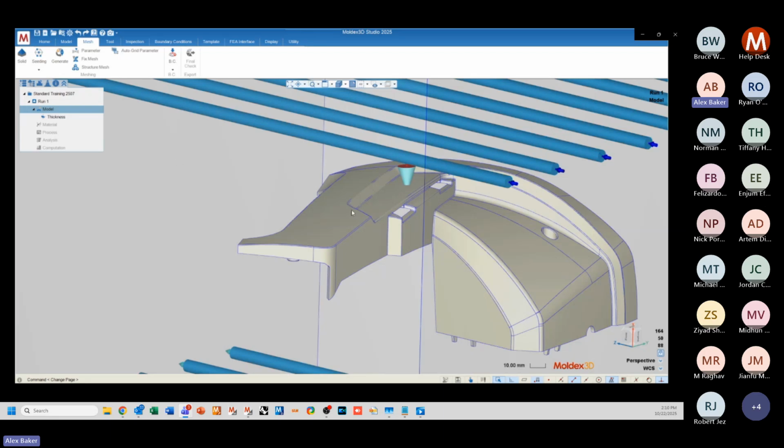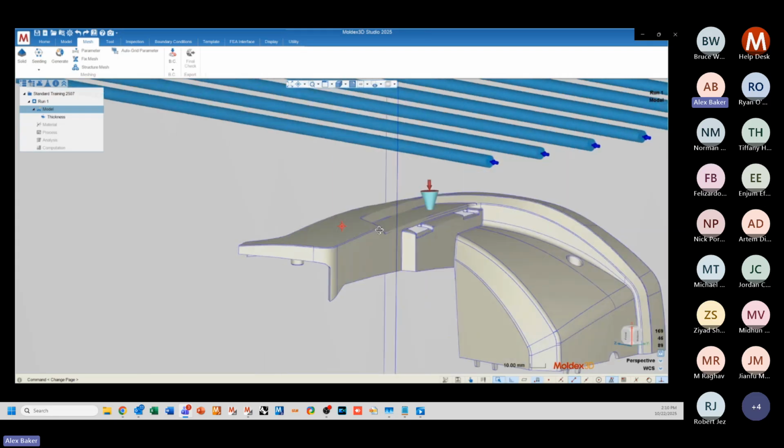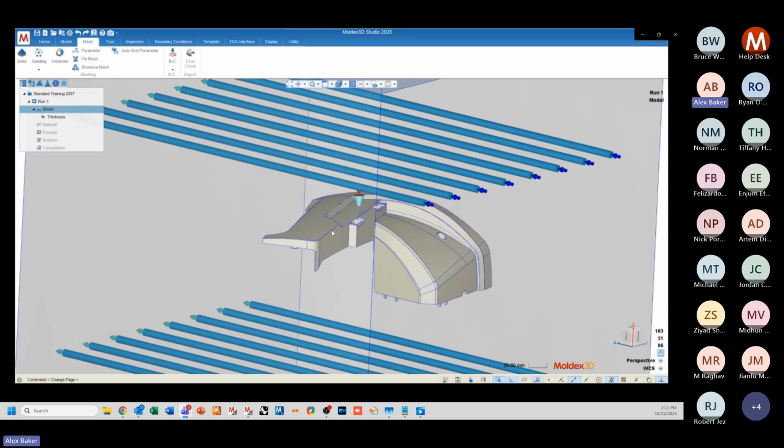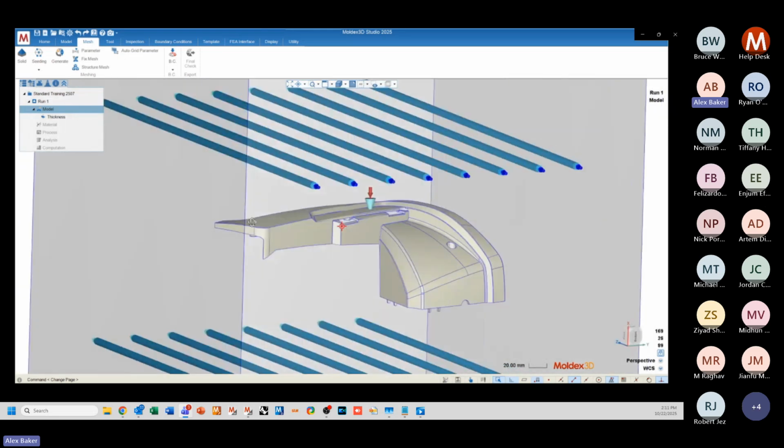That's your surface mesh. From that surface mesh, we're going to create a solid mesh through the thickness of our part. This is what we call the boundary layer mesh, and is the second type of mesh that will be created. The seeding function allows us to set up the template of our surface mesh. The surface mesh is going to be, like I said, the series of triangles. And we need to determine what the size of those triangles is going to be to optimize our solver performance and the approximation of the geometry with respect to how we create these triangular surface mesh elements.